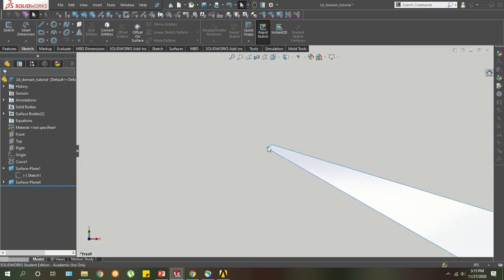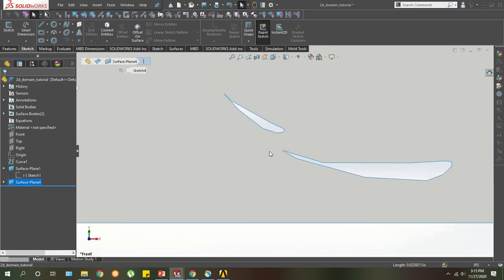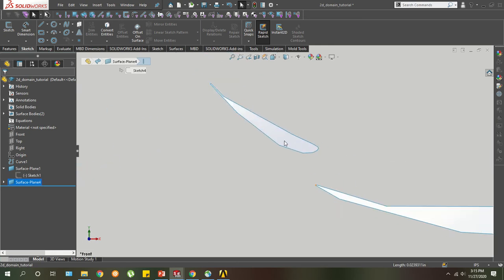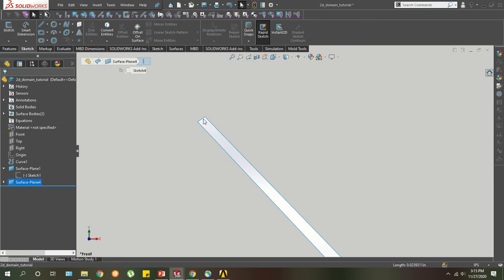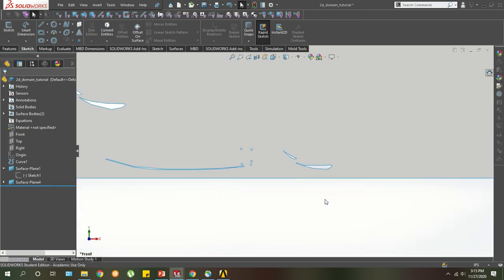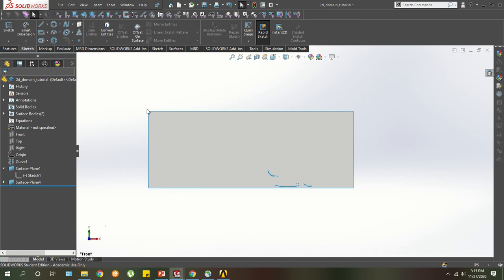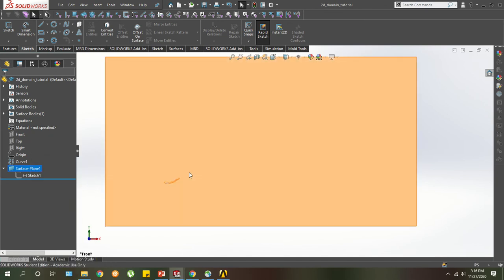You'll note the reason we had these lines that we had to add in is because, well, we didn't do that for 2D because it's a small domain. In 3D, it's extremely hard for the CFD to resolve a trailing edge that ends at a point, right? And so an easier alternative is to just change this length to roughly 1 millimeter to square off the trailing edge, and then the program will have a much easier time meshing. But I'll go into that later. All right, so that's a quick tutorial on how to generate your general 2D domain from an offset sketch, using an intersection curve. Just going to delete that, delete this. All right, return the sketch to its old conditions.